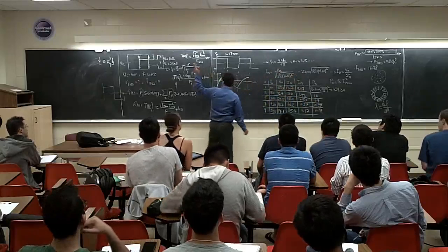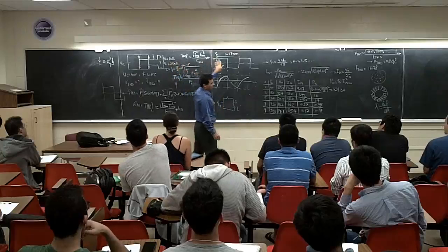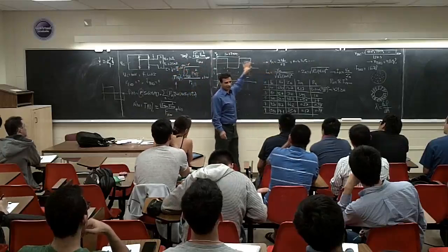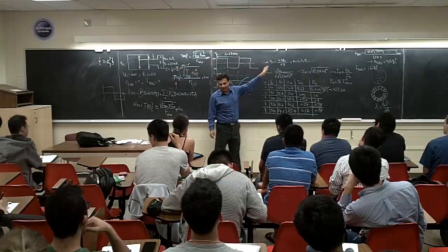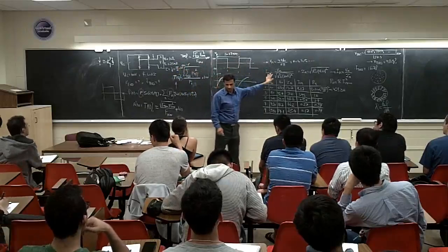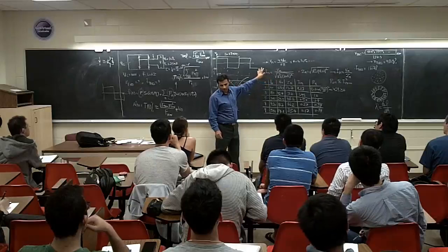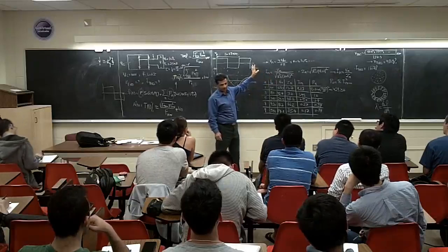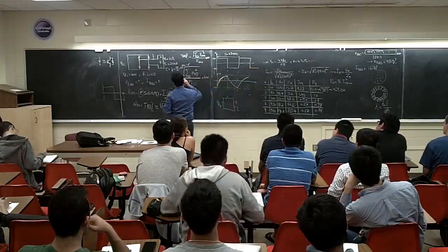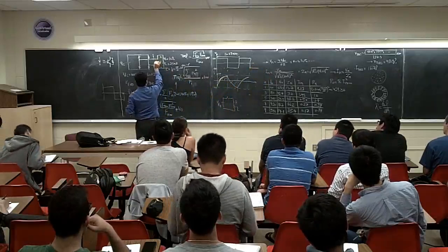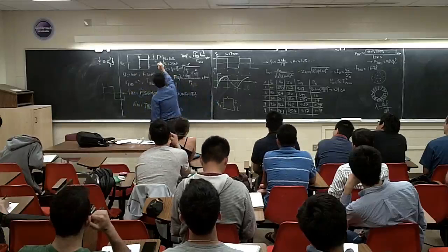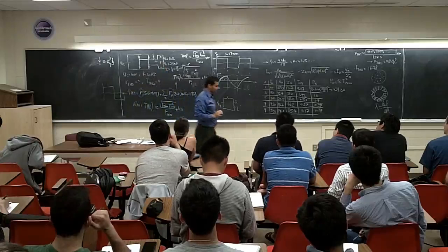If I put even 200 millihenry here, it's not going to affect this one, right? This one doesn't have anything to do with the inductor. Adding an inductor is not going to help us here. But what is going to help? Capacitor. If you had a capacitor here, it's going to clean up the voltage a little bit.